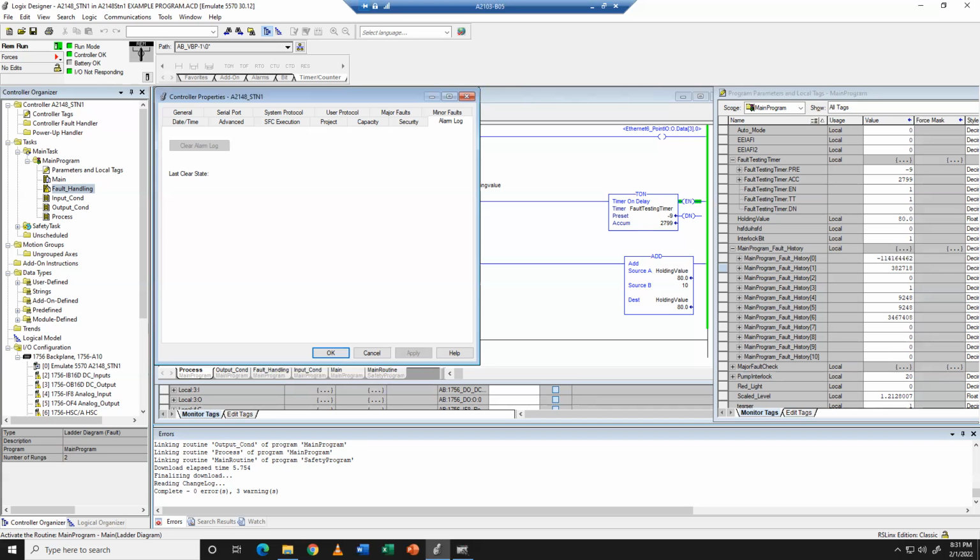Some of their uses, again: normally closed, typically used for safety-ish devices, things that you need to see are in a state all the time. So for a fire alarm or a heat alarm, or strain gauges, or safety bars and safety systems where as soon as it's activated, it opens up a loop, or you've got multiple switches. So like e-stops or safety stop buttons, those will be normally closed contacts, so that if you hit any one of them, it'll open the circuit no matter where you've hit it.